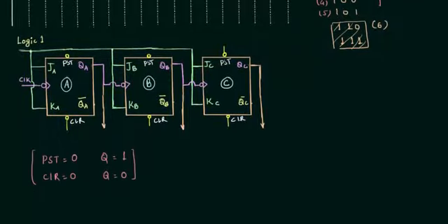Let's use a NAND gate here. This is my NAND gate, and I have used a 3-input NAND gate, and as soon as we have 6, it means if this one is my MSB, and MSB is definitely QC, and this one is my LSB, and LSB is QA. So I have QC, then I have QB, and I will use a NOT gate, and I have QA.